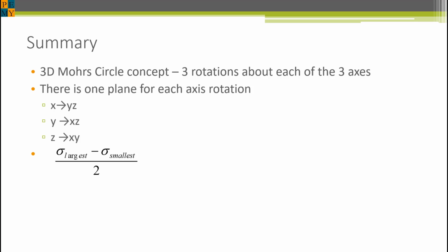This is because even a plane stress element is really a cube with a principal stress in the z direction equal to 0 and no shearing stresses on the z faces of the stress element. Because there are always three principal stresses, and even though sigma P3 is 0, the absolute maximum shearing stress may not occur in the XY, YZ, or XZ planes. It may be at 45 degrees to one of these three planes.